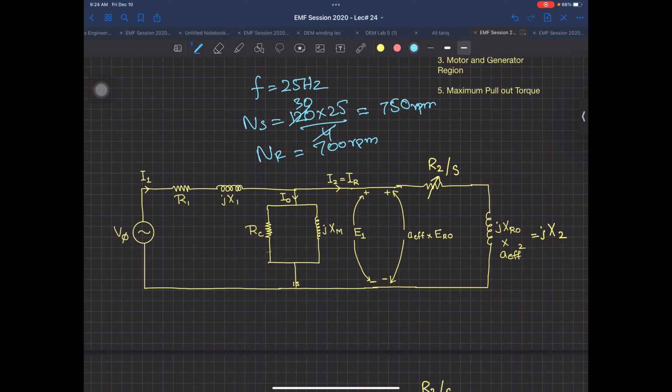By having a frequency change, I can now have a different speed. But the disadvantage is this, that the machine cannot run. Now there is only one way to do it, and that way is by also changing the applied voltage. What I mean by this is your voltage and frequency. Now this is the most important thing of this course which I am going to tell you today.